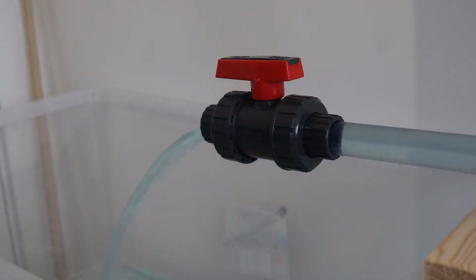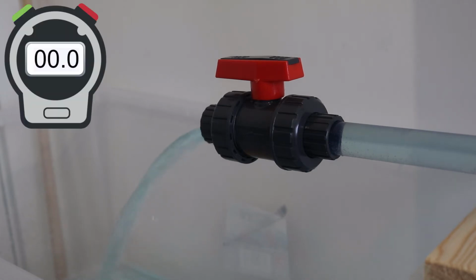I've set a flow in this system by opening the valve at the end of the pipe about half open. We can get the velocity in the pipe by measuring the discharge and using the volumetric method described in lesson 1 part 1.